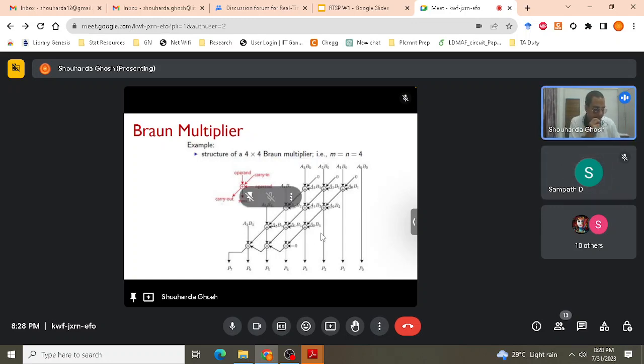So as you can see, there are three adders in the first row which have a 0, and then the adder of the last row just above P4 has another 0. So adding a 0 means adding nothing. At the end of the day, you are adding two bits actually. Note that this A0, A3, B3, these are not whole numbers, these are pure binary bits. It's either 0 or 1. It's the AND of the two bits of A and B.